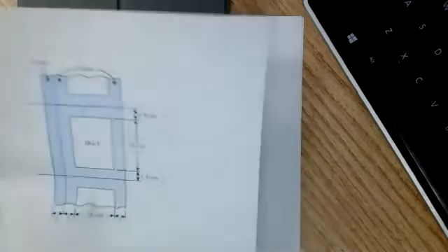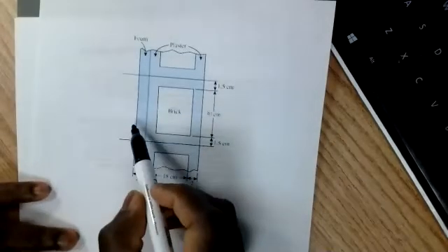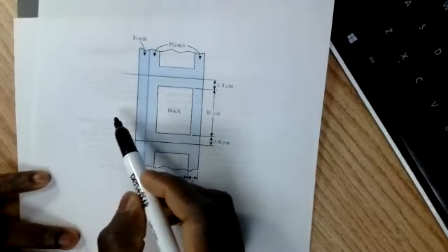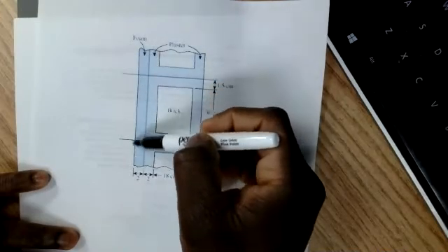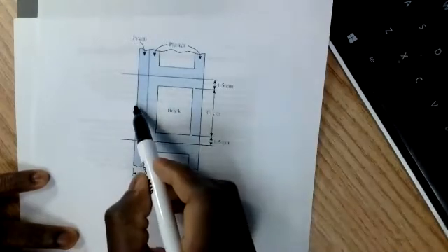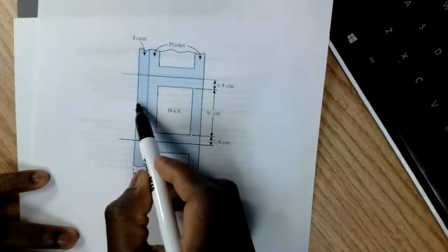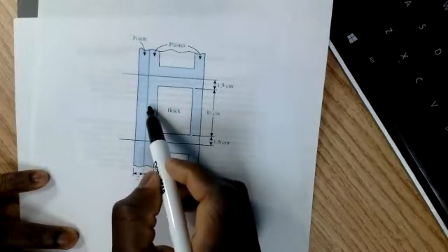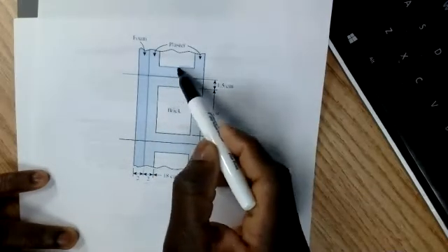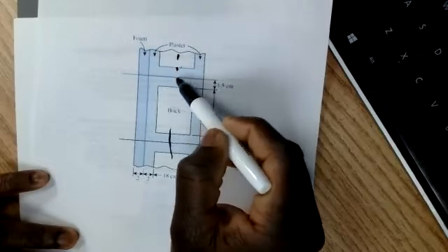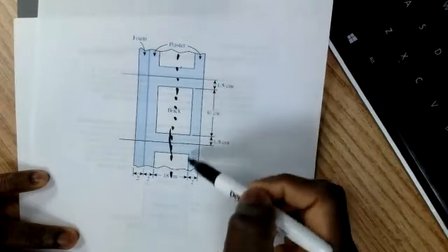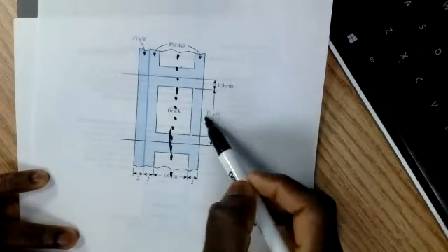So if we look at the question that we have been given, we're going to have convective heat flow or loss on this side. And there's going to be some resistance between the foam and the air contained on this side of the wall. Okay, so we have some resistance at this point. And between the foam and the plaster on the inner side, you have some form of resistance. You have some form of resistance in the brick and the plasters in this cross section here. Okay. And then finally, the plaster on the outside of the wall, and then between the plaster and the outside air.